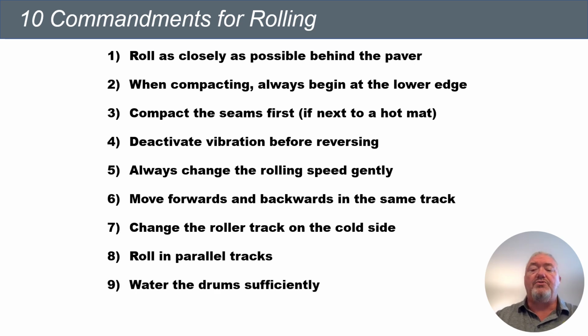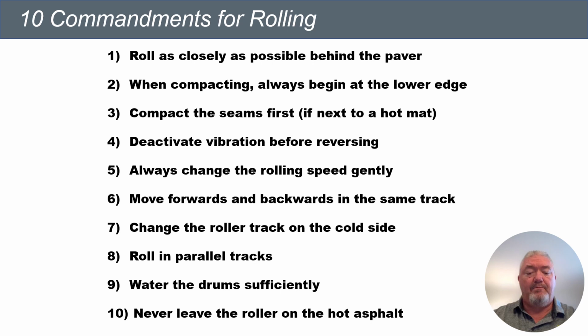We want to water the drums sufficiently. We only need enough moisture on the drums to keep from picking anything up. Anything more is a waste. Now, every manufacturer has a water management system, and we just need to control how much water we're putting on our drums so we're not overwatering and pre-cooling the mat.